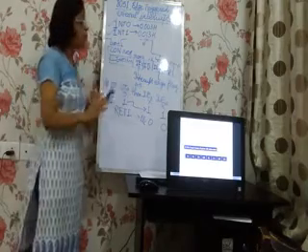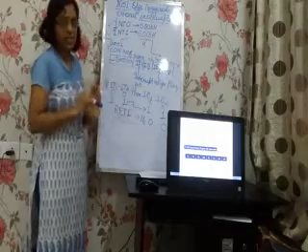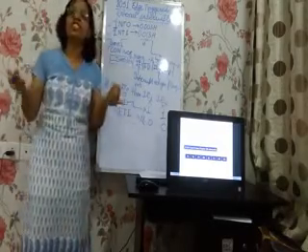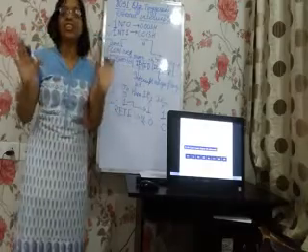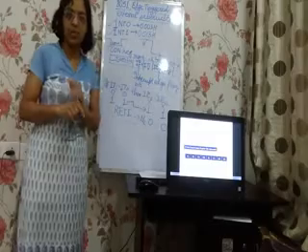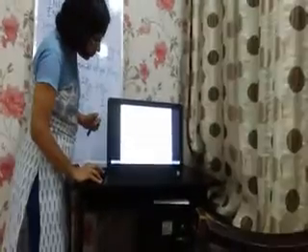I hope now you have understood the use of IT1, IT0, IE1 and IE0. So this is how the interrupts function as edge triggered interrupts. Now, to understand this better, let us take an example. So come to this slide now. The same thing is given on this slide. You can go through it.